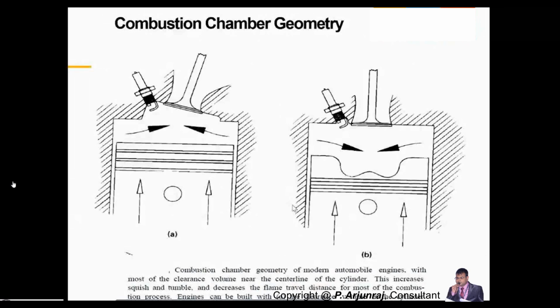You're going to design the combustion chamber with different types and different configurations, ensuring that you have different varieties like swirl, turbulence or squish, irrespective of the form. So you are ensuring that you are providing more volume, and providing the place where the complete mixture is going to take place. Mixture in the sense of air and fuel mixture.